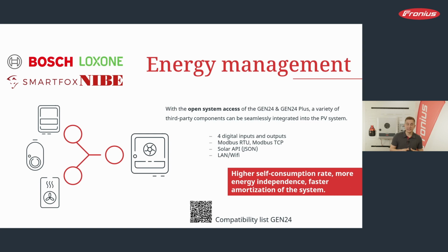For example, you can control an external heat pump over, for example, our digital I/Os. We also have direct communication with some of the manufacturers via Modbus TCP/IP, so over our Solar API calls. And of course, the inverters always have LAN and Wi-Fi to make sure that you have an internet connection, a network connection to SolarWeb.